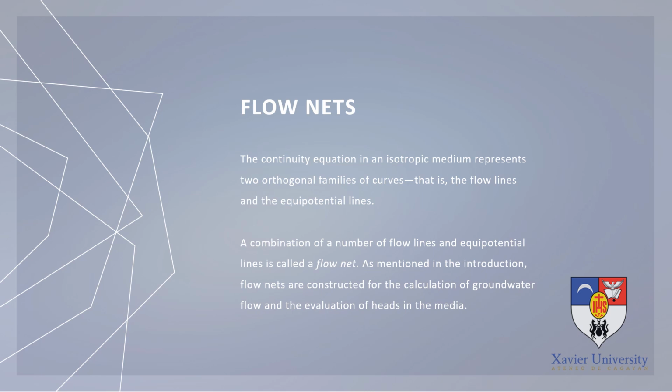So as mentioned in the introduction, flow nets are constructed for the calculation of groundwater flow and the evaluation of heads in the media. So therefore, flow nets will enable us to calculate the groundwater flow as well as the heads, and it enables us to evaluate the pressure heads inside our permeable soil layer.